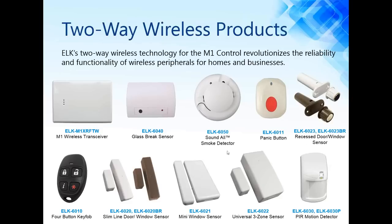And once again, the 4-button fob has an LED on it, and once the signal is received, you can check the status of the system by pressing the third button, which we call the inquiry button, has the eye on it. You press that. If the LED turns green, the system is disarmed. If it turns red, the system's armed. If it's flashing red, that means the system has been in alarm. So it's a great visual indication before walking into the residence. You want to check the status, or if you've just walked out of the residence and couldn't remember if you armed or disarmed, we now give you a way to check the arm-disarm state of the system, as well as whether it has been in alarm.